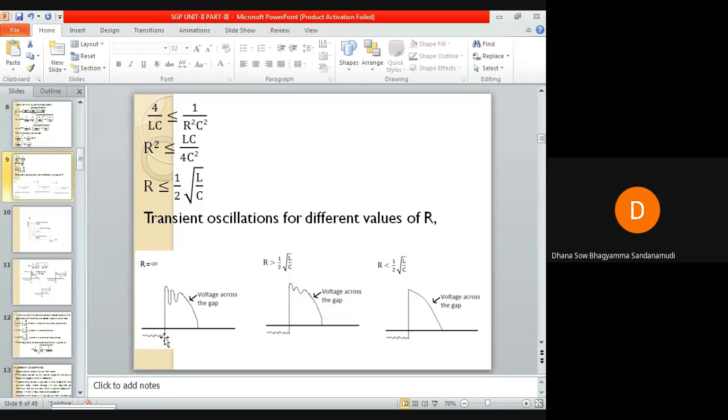If you observe, this is the arc voltage I am showing you. When the arc is interrupted at some current zero, the restriking voltage that appears across the circuit breaker contacts is a transient voltage which will have oscillations. If you have attended my previous classes, you will remember. In the lower image, this is one half cycle, this is another half cycle.